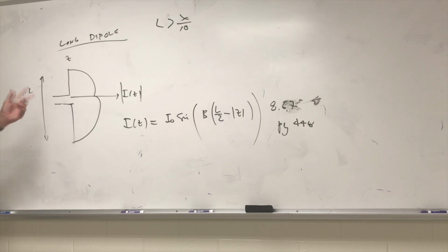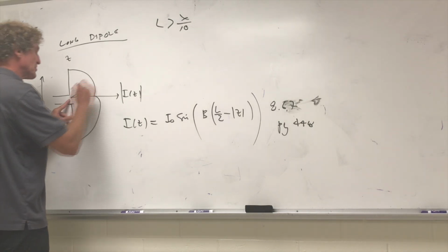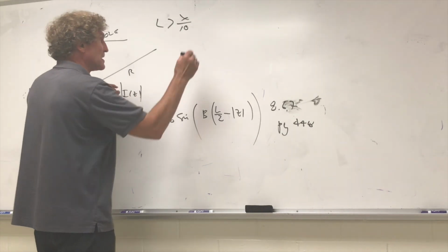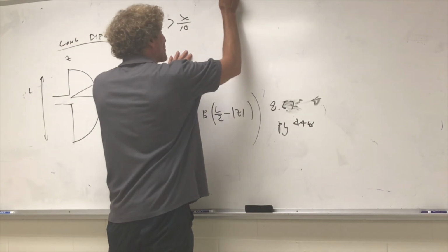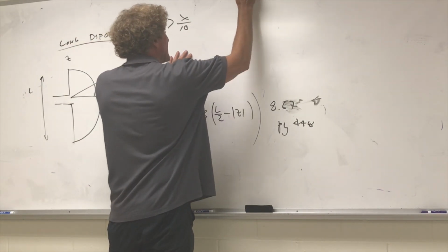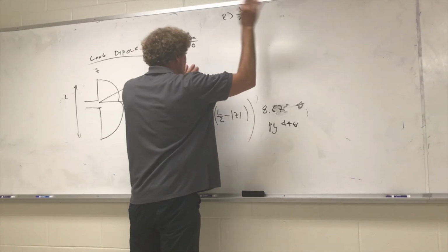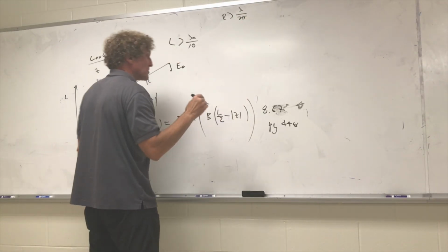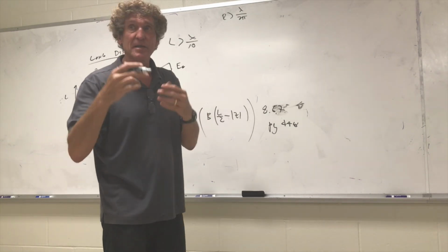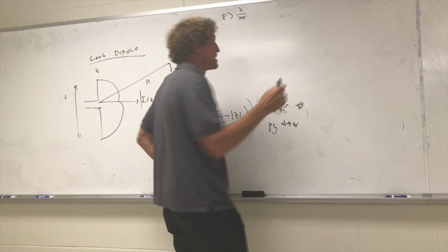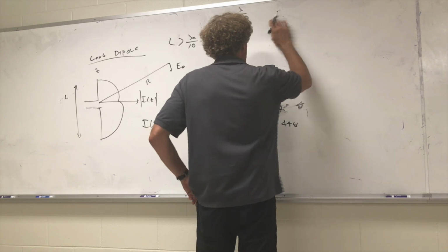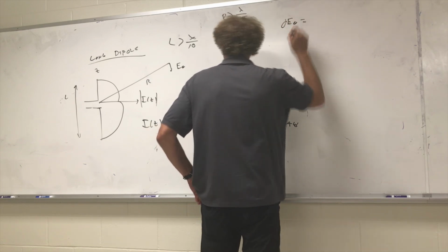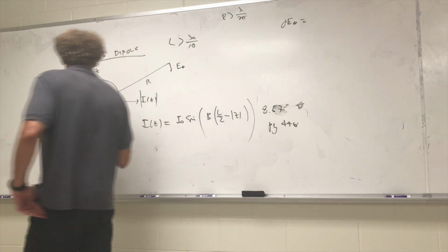Because that integral, I guess I could do it one time, but if you're out at distance r and you're in the far field, so let's assume we're at r greater than lambda over 2 pi. So we're in the far field, and we want the electric field. The way that they generally say to calculate it, it's going to be in terms of an integral, but we could say the differential electric field that would result from this, here's how we do it.